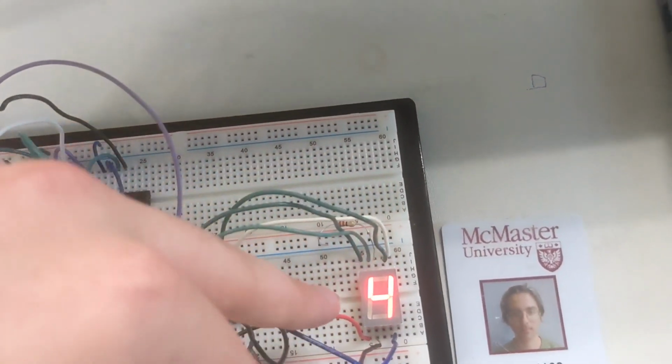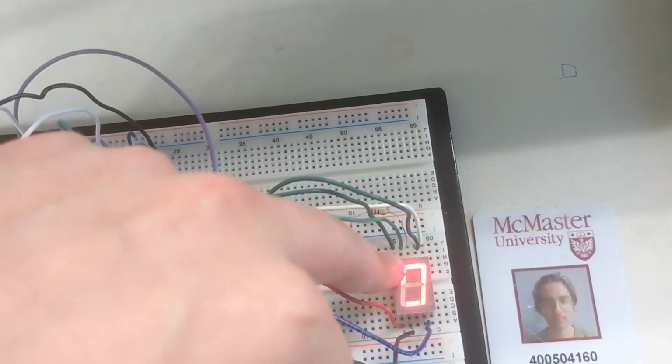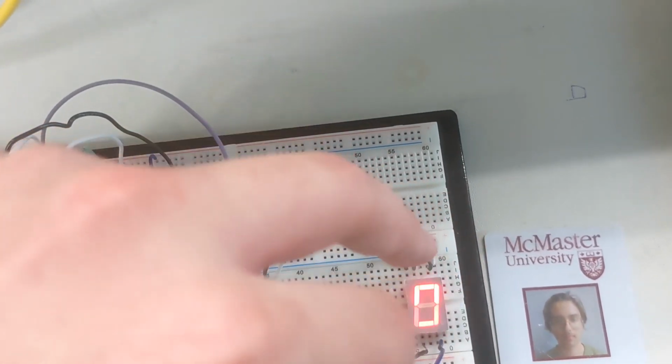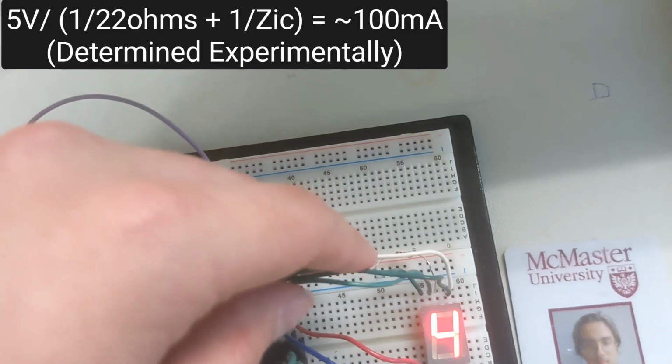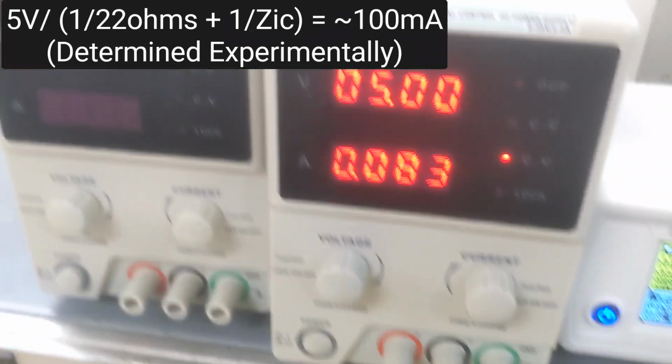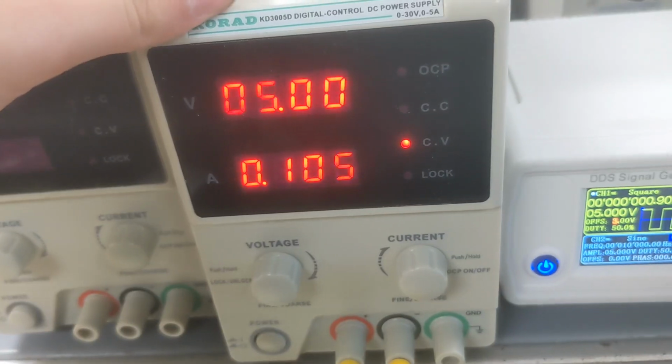And the tolerance of current on the 7-segment display is around 150 milliamps. So we used a 22 ohm resistor to ground it so that our amperage isn't too high.